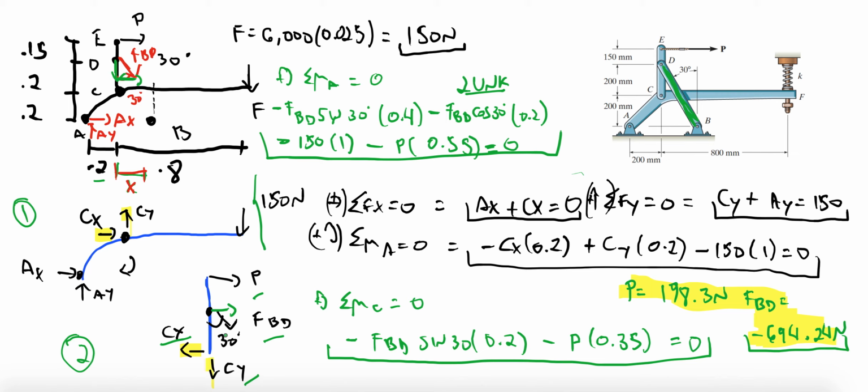By noticing that, you should quickly go back and fix it wherever you put it as not a two-force member, right? So for instance, before I had this split up in two components. That's not incorrect, but that's just going to add one more unknown that will not allow you to solve this problem. So that becomes an issue, right? So once you realize that, you recognize that all you're going to need now is just one more equation.